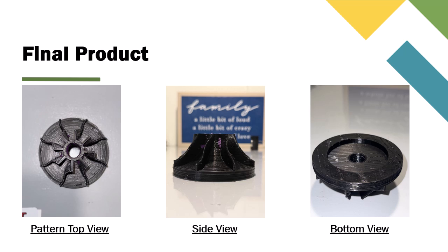Also, some of the fins had a slight wiggle to them, and they were thin and fragile, which made casting harder. In the future, we'd probably tweak the design for better castability, like thickening the fins or adjusting their geometry a bit.